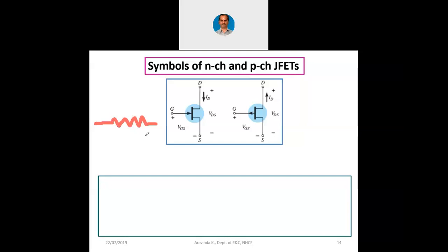Okay. Similarly, when you see a capacitor symbol, what do you understand? You will understand that current comes all the way. Let us say electrons come all the way from this side. When electrons come all the way from this side, they don't find a path here because there is an insulating material in between the two plates of the capacitor. That insulating material is called a dielectric medium. Why is it called a dielectric medium? For example, let us say electrons come from this side. Electrons don't find any path. Electrons get accumulated here. Electrons cannot go back because there is an EMF there. There is an electromotive force which is pushing the electrons this side.